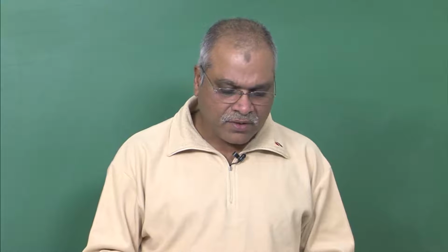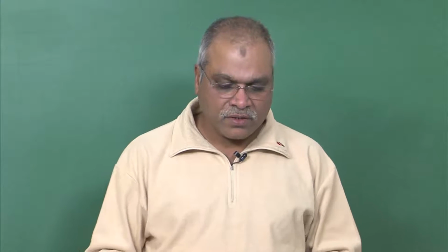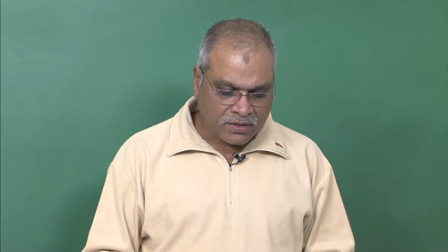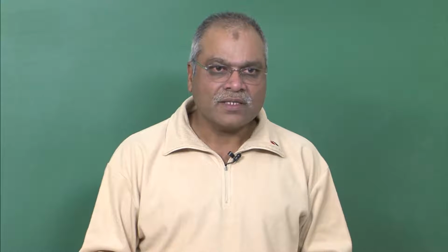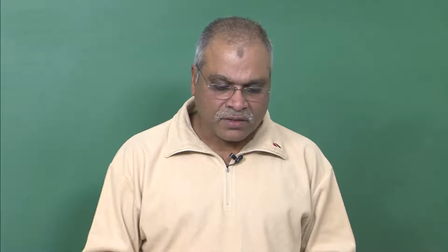Now, this is an example of the shear zone which we located close to again Chandigarh. This is what you will find in the shear zone. You will have very shattered rock in the shear zone because of the deformation, and this will result in extreme problems when you are putting a structure on this, because they do not have good shear strength along that, and if there is a movement on this, then you will have problems on the structure sitting right on the top of that.